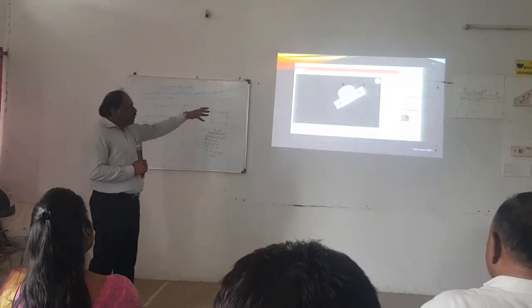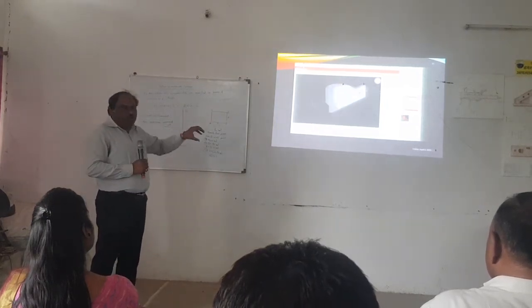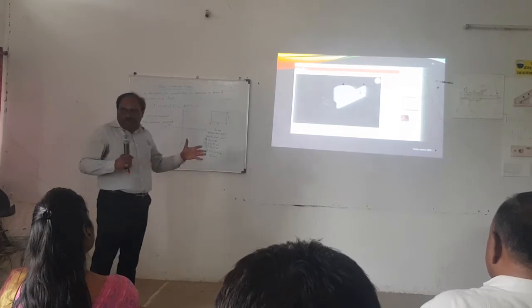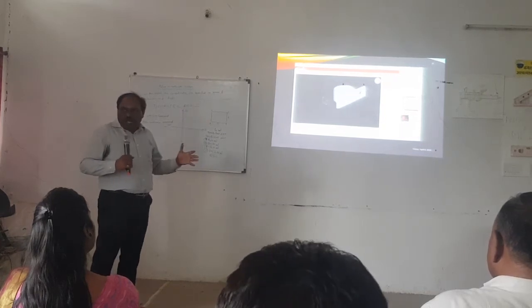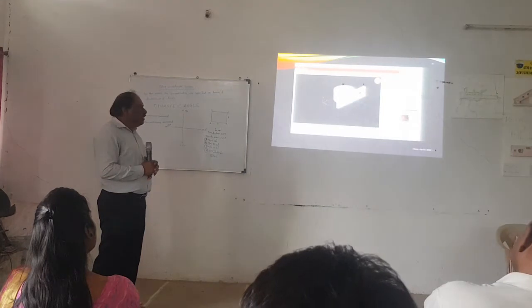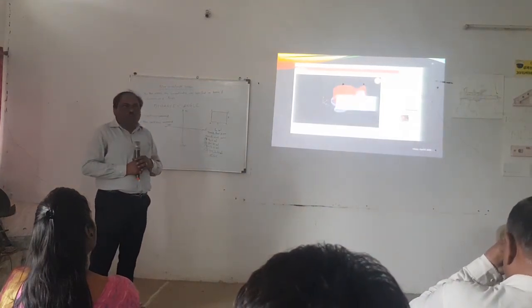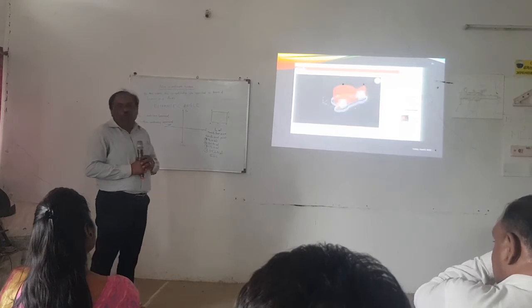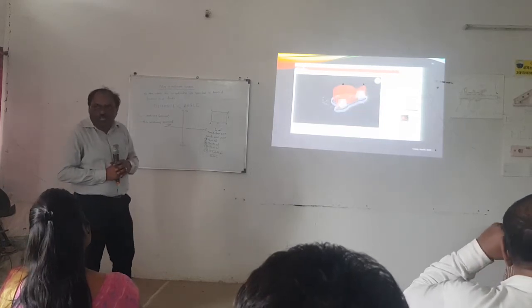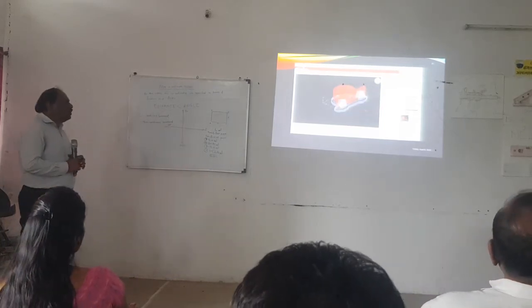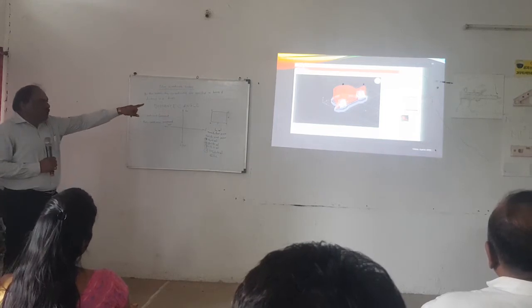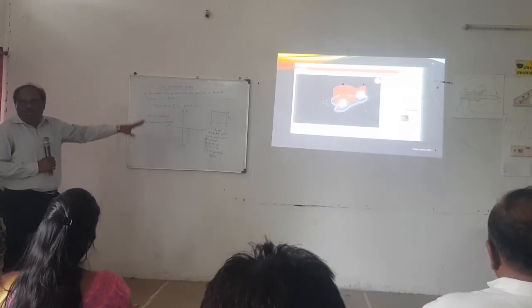Then it will automatically orient that particular component. You can reduce the scale of the component, you can make it small or large depending upon your requirement. In this particular machine, we have scaled down the component to 1/4. A 0.25 scale was taken. Then you can see that is the support material and the red one is the object material.